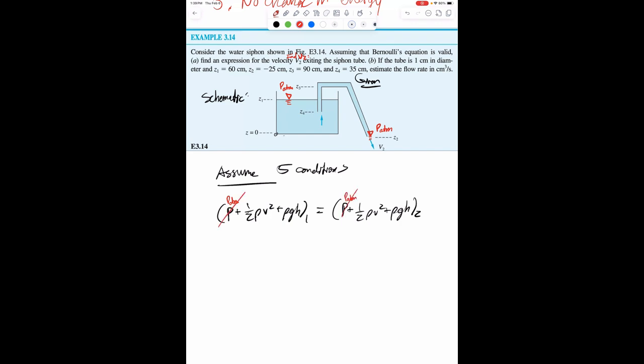One thing I forgot to talk about real quick is within this cup, before you enter the straw, which obviously the fluid's moving in a streamline, right? While you're in the cup still, that's hydrostatics. And you can imagine hydrostatics as everything that's not moving being part of the same streamline, essentially. That's why we can use Bernoulli's, because it's all part of the same streamline. In hydrostatics at location 1, hydrostatic means V is 0, so we can cancel this term too. There's only 3 terms left we have to deal with.